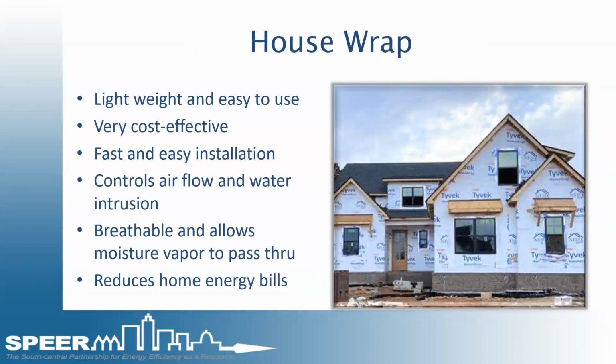So another thing that's bounced back a little bit, it used to be more commonly used, at least in DFW, and then it had a resurgence when there was a shortage of T-ply, is house wrap. It's light and easy to use. It's very cost effective. It's fast and easy for installation. It does control airflow very well. It controls water intrusion very well, but it's still breathable and allows moisture vapor to pass through, allowing homes to dry from the inside or to the outside as well. It also helps reduce home energy bills by stopping airflow through there for infiltration.